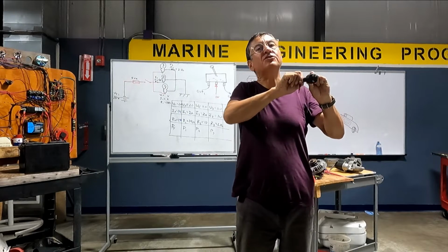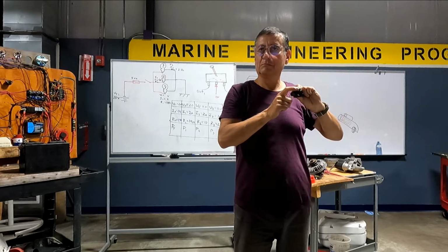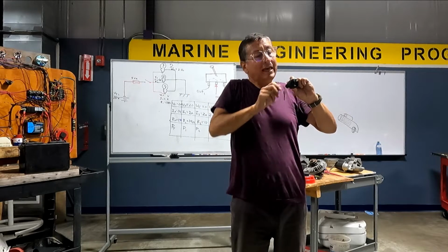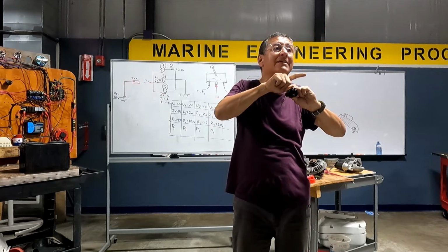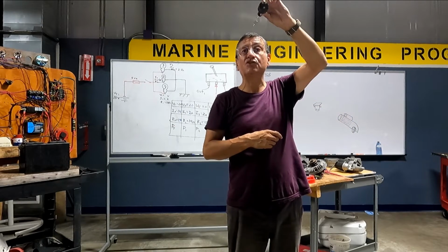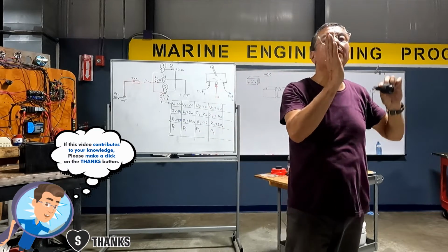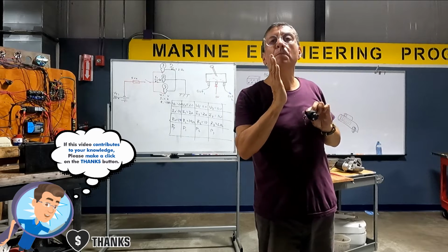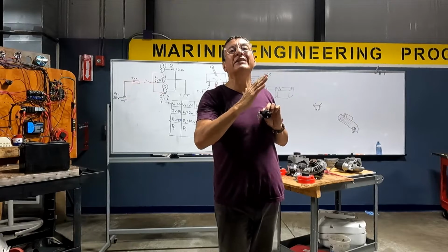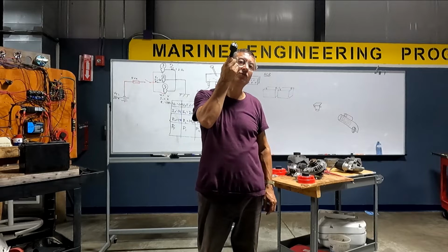When I select the first position, it is ignition, and I activate all the lights in the dashboard. In the second position, I send the signal S to the start motor. Now we are going to connect this ignition switch. How many positions does the ignition switch have? Two positions. The first one is ignition, permanent. And the second one is start or signal, momentary.